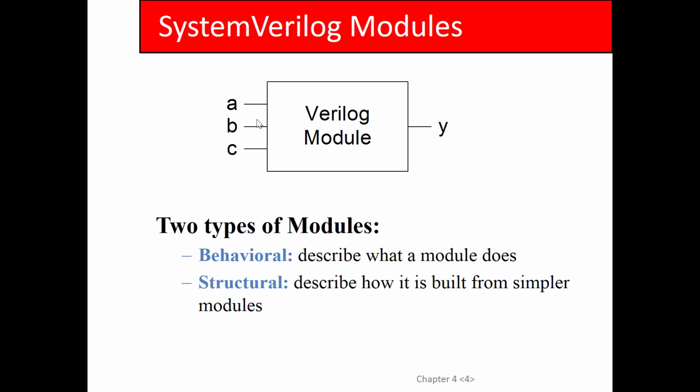The challenge with that is that when you have a wire that's connected to a module, it will be known as one name potentially when you connect it to that module, but when you go inside that module, like when you're debugging, for instance, simulating, you drill down inside that module and it may be called something else, even though it's the same signal. The reason this is confusing is because you have to think of what the context of all the wires is when you're debugging, when you're designing.